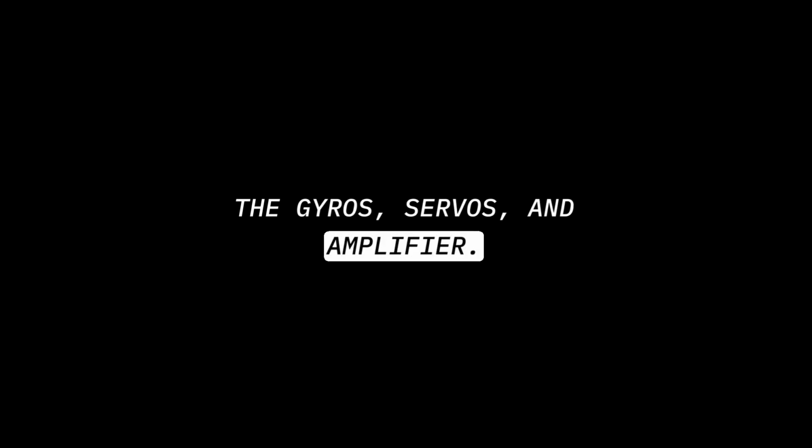What are the basic components of an autopilot system? The gyros, servos, and amplifier. What are the sensing elements of an autopilot system? The directional gyro, turn and bank gyro, attitude gyro, and altitude control are all the sensing elements. These units sense aircraft pitch, roll, and yaw to automatically generate signals to keep these movements under control.